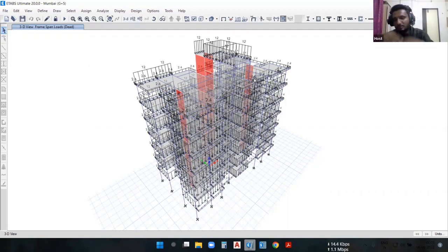So there is a check for the deflection in the slab. We'll check in that particular lecture whether the thickness we have considered for the slab is enough or not to resist the super dead load and the live load that will be acting on the particular slab. Let's say the deflection is more than the limit as suggested as per the American code. In that case, we have to increase or decrease the depth of the slab. We'll discuss that also.